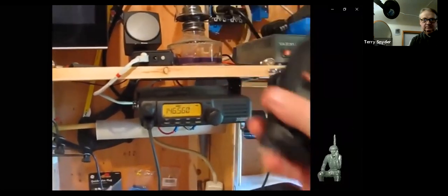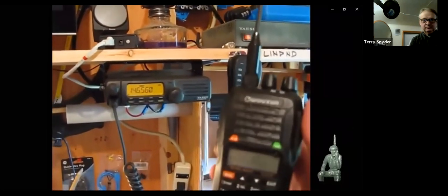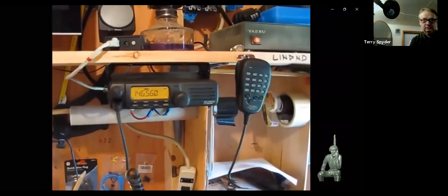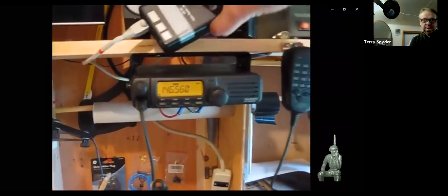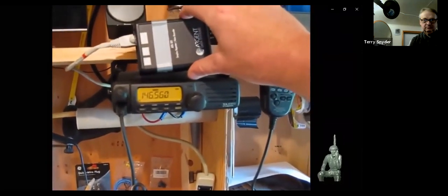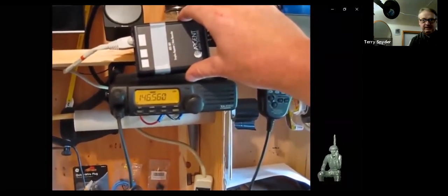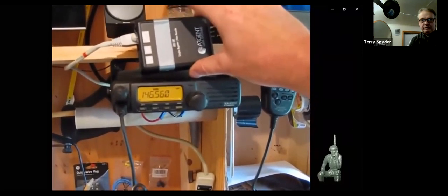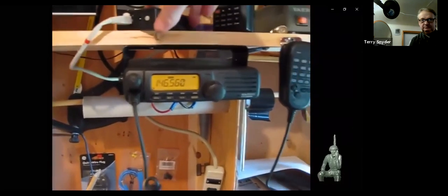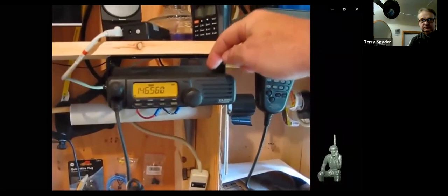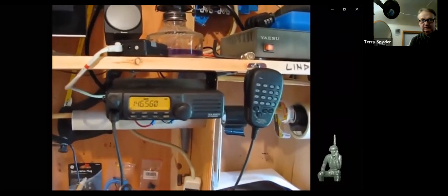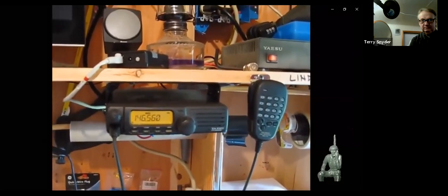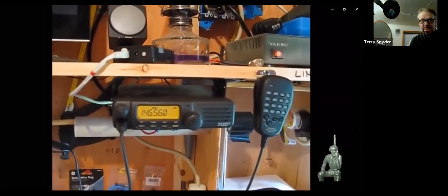I'm going to use the Ocean radio, and how the simplex repeater works is I transmit into the radio. The radio passes that transmission to the simplex repeater, which digitally records that audio. And when I'm done transmitting, this box will key or make this radio transmit, and it will repeat that message. So here we go for the local test, and then we'll go off the map and show you how this works from 10 miles away.